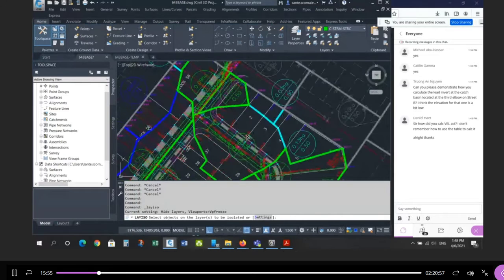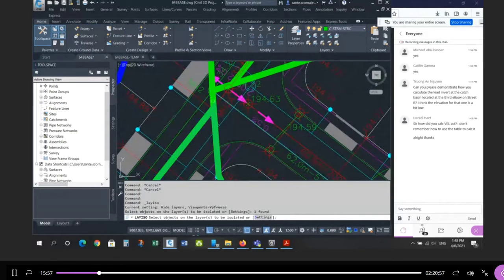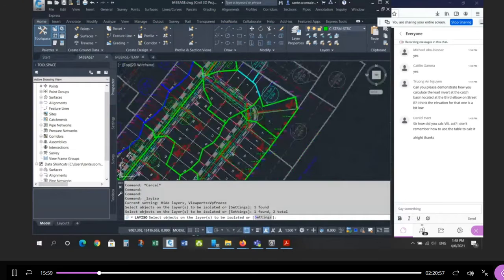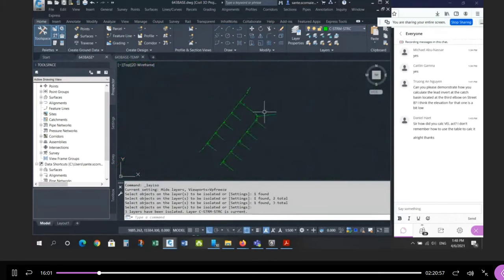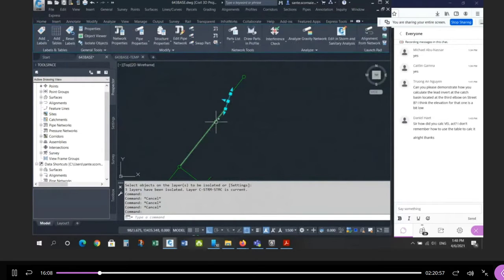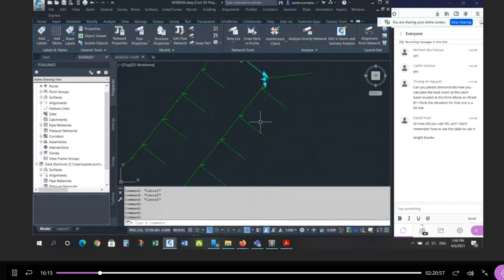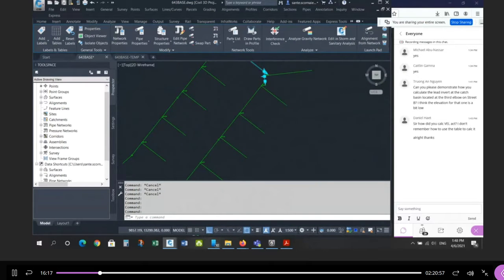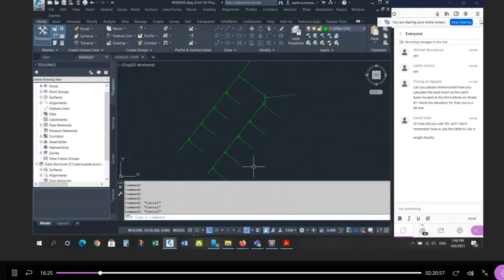So in the plan view, what does that look like? Let me show you. Let's look at the sewer system with the rear lot catch basin leads. In this sewer system, this existing 825, I'm going to leave it alone. I want to make this one flatter. I want to make this one flatter. I want to make this pipe flatter, and I want to make this pipe flatter. And by doing that, it's going to lower the system. I'll be able to lower these two pipes. So let's look at it hydraulically now.